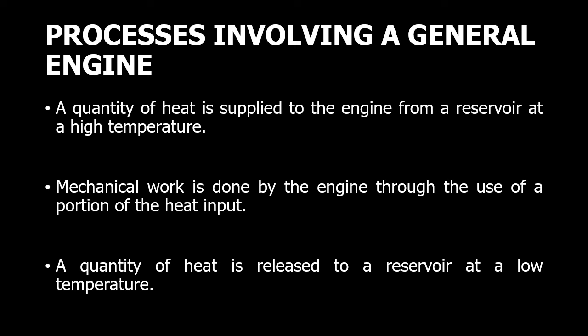So the development of a general statement for the second law of thermodynamics was based in part on the study of heat engines. A heat engine is any device that uses heat as input and provides mechanical work as output. The basic idea is that a heat engine, either a steam engine, internal combustion engine, or jet engine, is that mechanical work can be obtained only when heat flows from a high temperature to a low temperature.